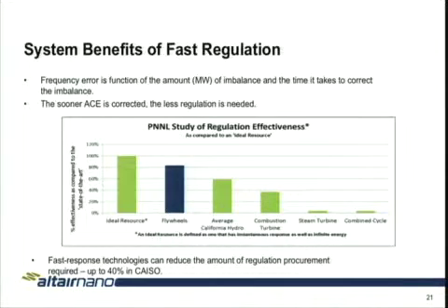This would be unlimited power, unlimited energy, fast response, and then how does it compare to other types of technology? In California, we're pretty blessed with a lot of hydro capabilities, and we utilize that, and also a lot of pumped hydro, which is used for regulation, both frequency regulation and also spinning reserve. And that actually helps keep our prices pretty low. Our frequency regulation prices in California are somewhere down in the $10 to $20 per megawatt range, relatively low because of the hydro, which is very good.